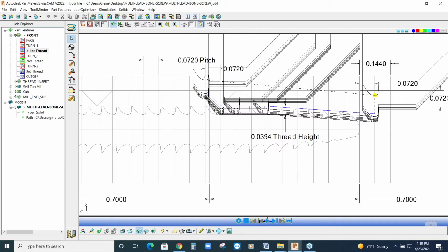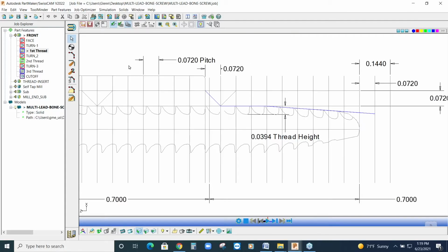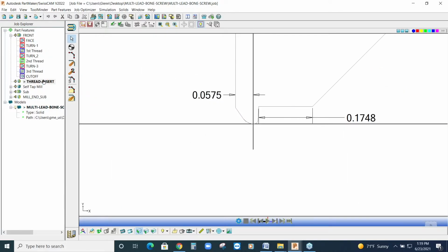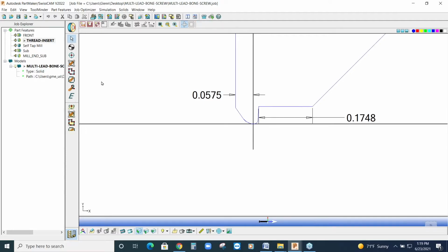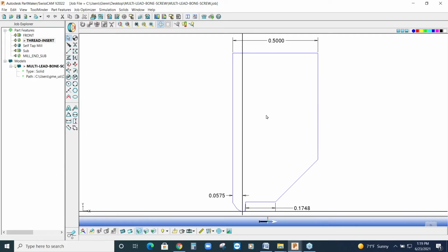It's slightly different, but the only thing that is really different is if you've used the user-defined tool shapes, you create a copy of your tool. We'll go to a full view of this. So in this, we've defined a tool shape that matches what's going to go into my machine, and we set the distance in front to get to 0.